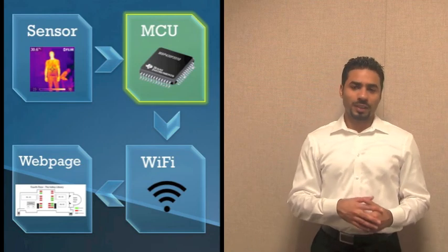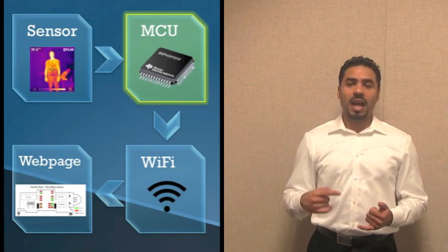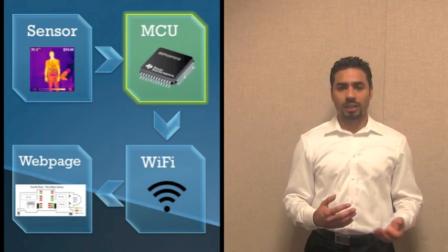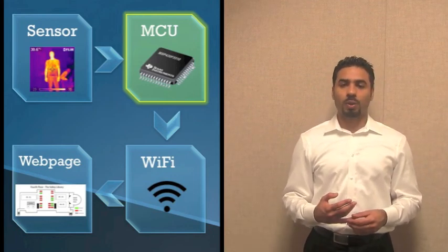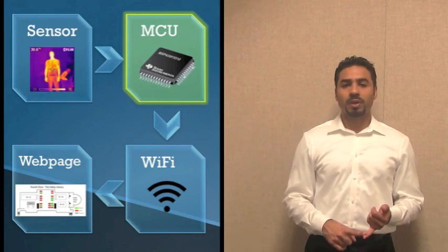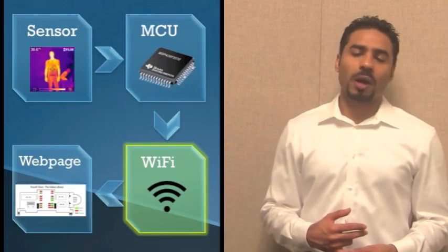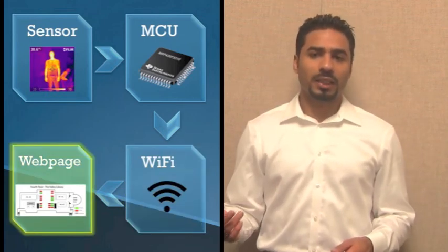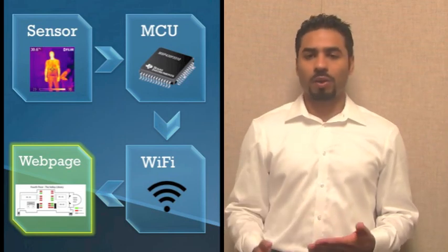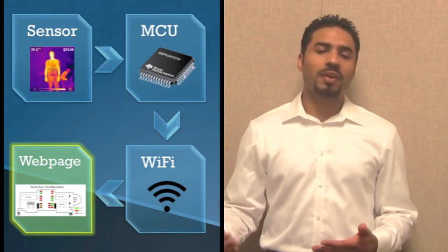If the microcontroller receives a digital high from the sensor, it processes the data and decides whether the table is occupied or not. Then it sends two pieces of information to the Wi-Fi module: a unique serial number, and a status. The Wi-Fi module is connected to a server where there is a database that receives this data and stores it. Then we have a web page that takes this data and represents it graphically to students.